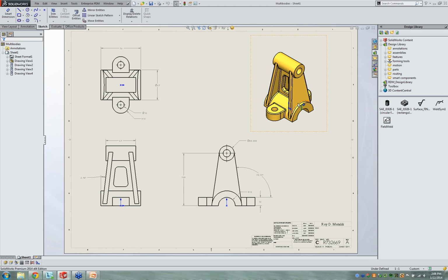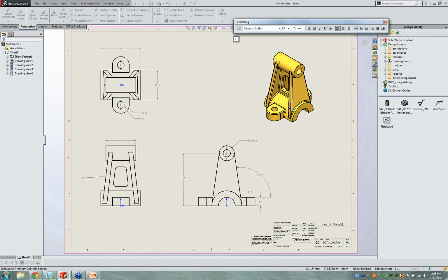We've got some fillets. Let's focus on those, on several of the edges. All these really are is cosmetic fillets. They're applied to round over those edges. They're not really structural fillets of any kind. So a common example of something you might call out on a drawing is perhaps a note explaining exactly that. So let's go ahead and create a note here. I'll grab my note. And all I'm going to type here is that these are cosmetic fillets, all cosmetic fillets, 1 millimeter unless specified otherwise.